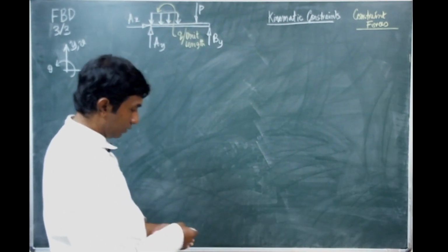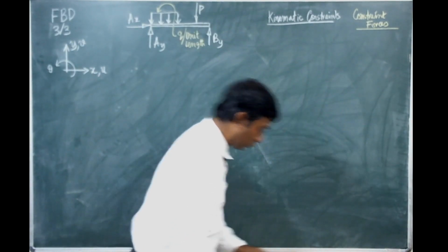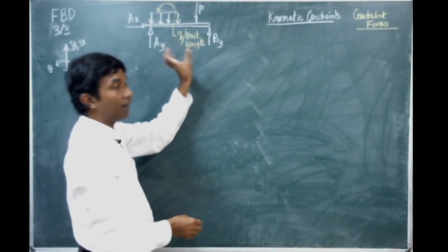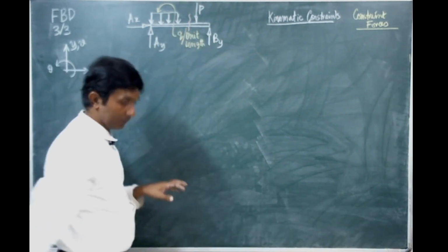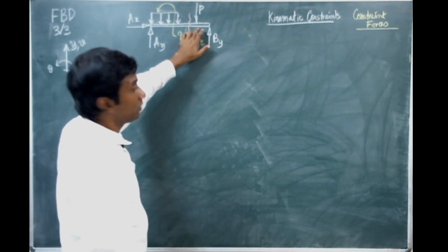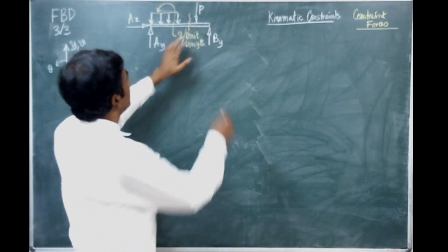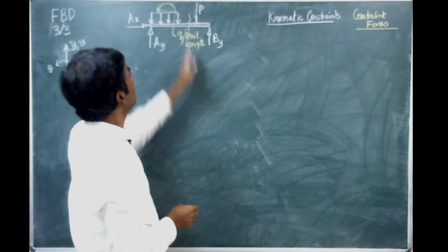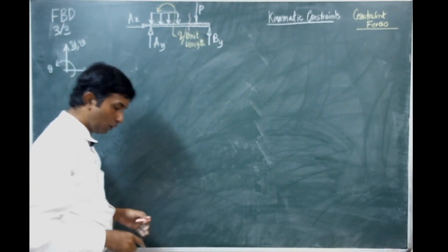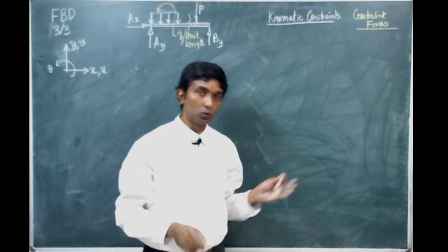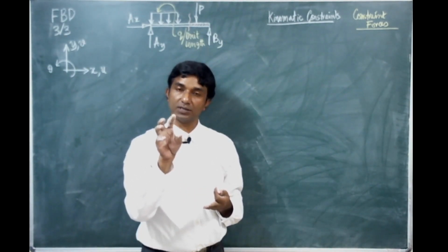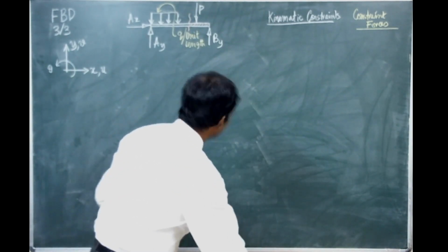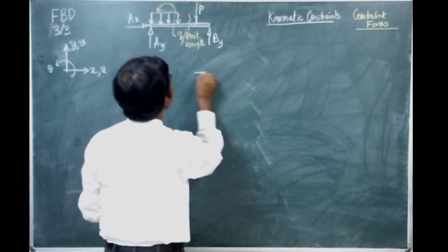So now our notion is a little bit different. We are going to consider the free body diagram of a part of this beam. Let us consider a section and try to draw the free body diagram of the right part with respect to the assumed cut section. You remember rule number 1, that the portion of interest you need to draw, and delete all other parts.